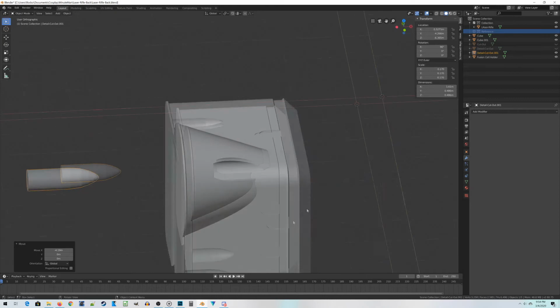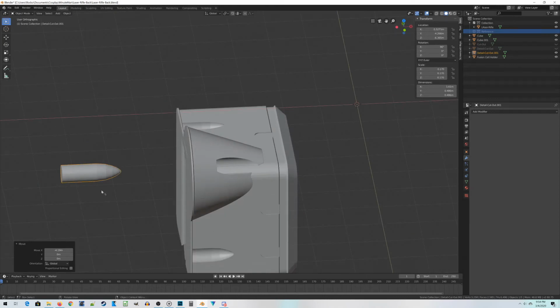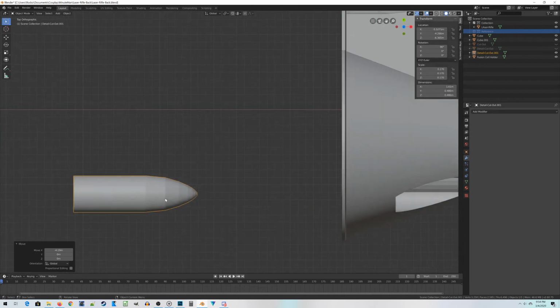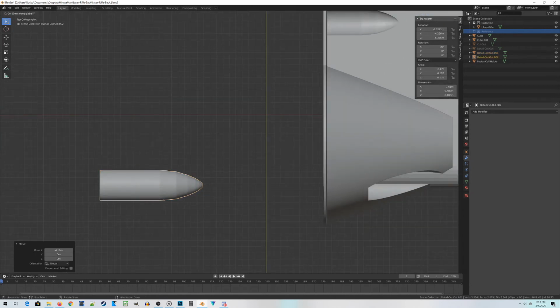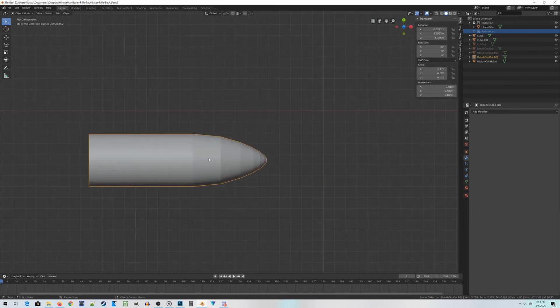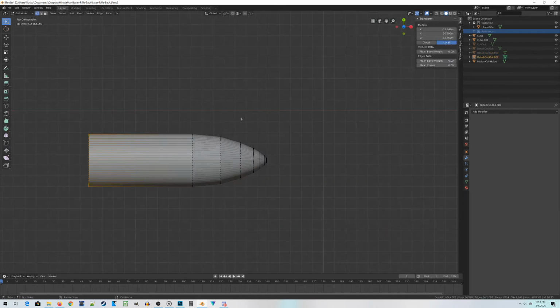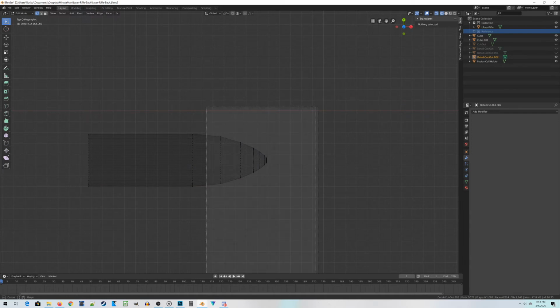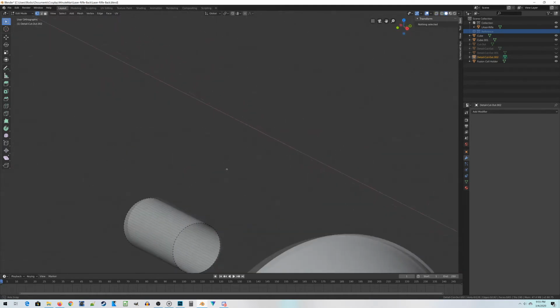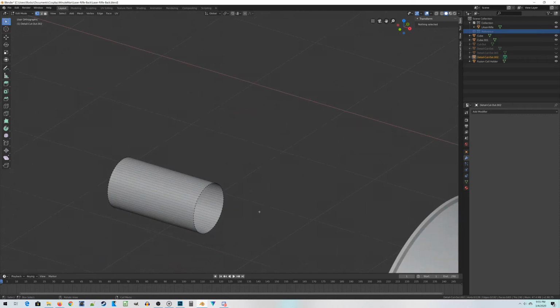Cool. All right. Now I need to add a little extension piece right here, and to do that, I'm going to take our detail cutout. I'm going to duplicate it just because I don't really need it anymore. But you know, there's no reason to delete stuff. Let's jump into edit mode and get rid of all this end here that's all kind of scaled down. So select those vertices, press X, choose delete vertices, and now I kind of have just an open cylinder.